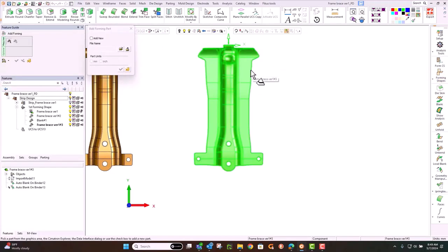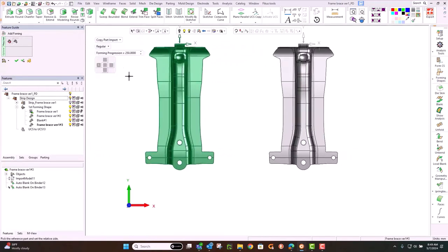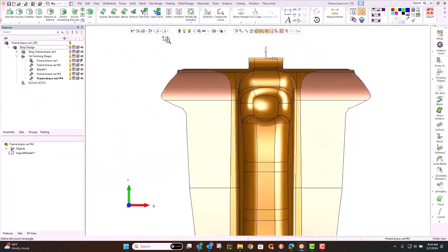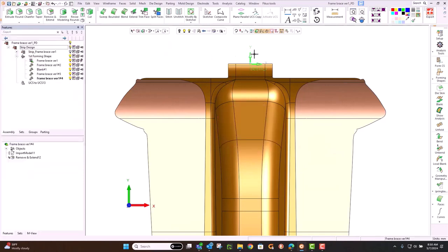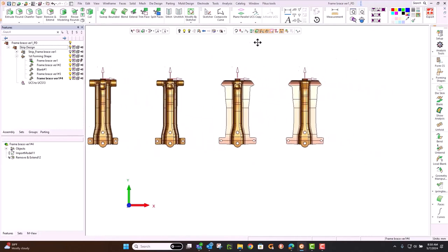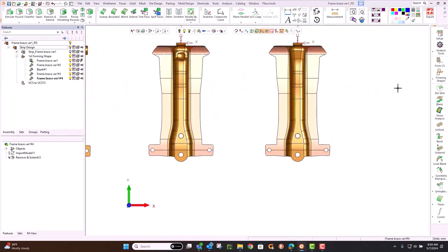Here in the center, you see there's a dimple. All right, so perhaps that was placed in because we needed to stretch that area, understanding that there's the wrinkle tendency. Let's do that in one single step. So in this case, we'll go ahead and take that out of our sequence of operations. Now we've got our forming condition just for that particular dimple area. Moving on, we'll do another one.